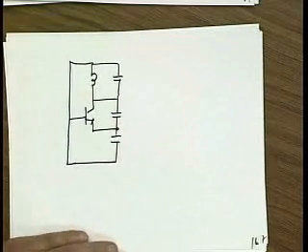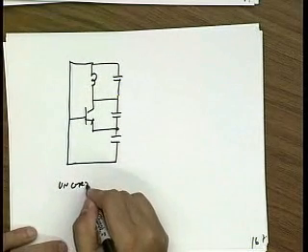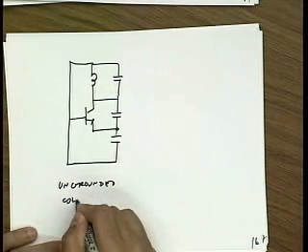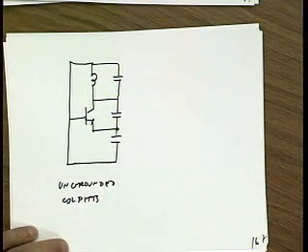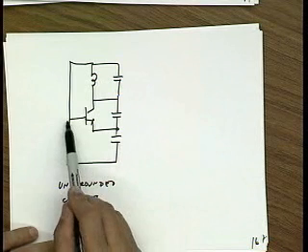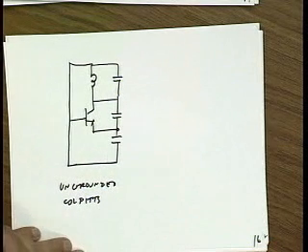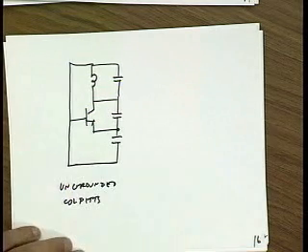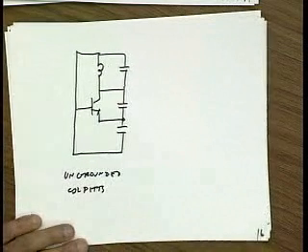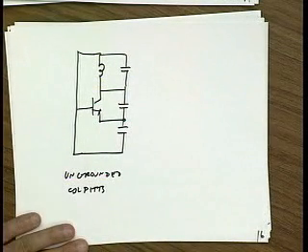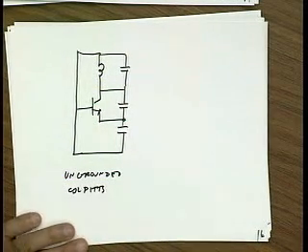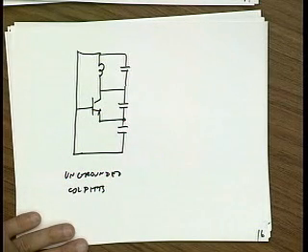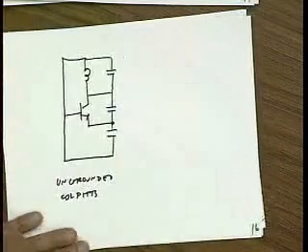So now, this is an ungrounded Colpitts, and if I ground the base, I get the Colpitts oscillator that I just saw, but I could also ground the emitter, right? Or I can ground the collector, and the operation of the circuit shouldn't change in a fundamental way, right? A ground is just a ground. It's just a reference point. So in theory, I can just ground any point and produce another oscillator.